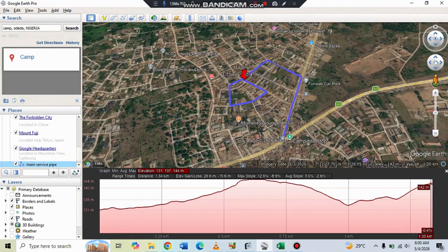So this also means that you also need a place where you can have your storage tanks. So it is possible that your reservoir may not be located at this point. It may be located somewhere lower because it needs to be closer to the source of water, whether it is a river body or stream or groundwater sources such as artesian wells. So that means that if you have that, you must have a high lift pump that will lift the water from the reservoir to the overhead tank.